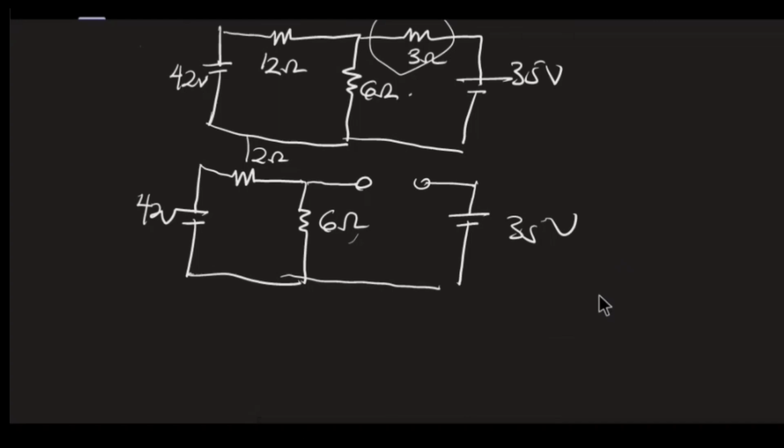I have removed the resistor, and Norton is saying to replace the resistor here with a short circuit current. For the short circuit current, we close this part and we assign a direction for our current, because the current will have a direction. The current is moving this way. The current is called IN, that is Norton's current. So we have assigned the direction for the current.